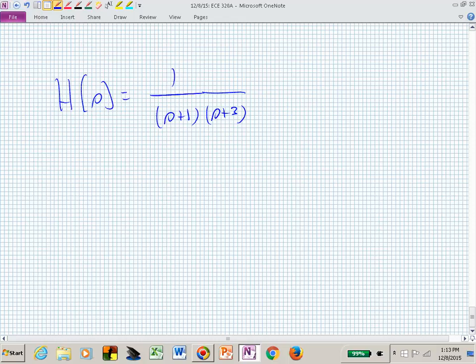1/3. So we probably would say, you know what, let's put this additional piece in time constant form so we don't mess up our gain. So we might put this in like that. But you know that that would be an s plus 3 factor, and the 3 would come upstairs, and we have a DC gain of 1 for this filter.